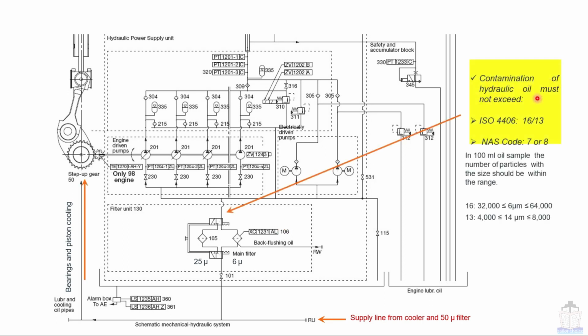Now contamination of hydraulic oil must not exceed, as per ISO 4406, 16 and 13, in a 100 ml oil sample the number of particles within the size range.